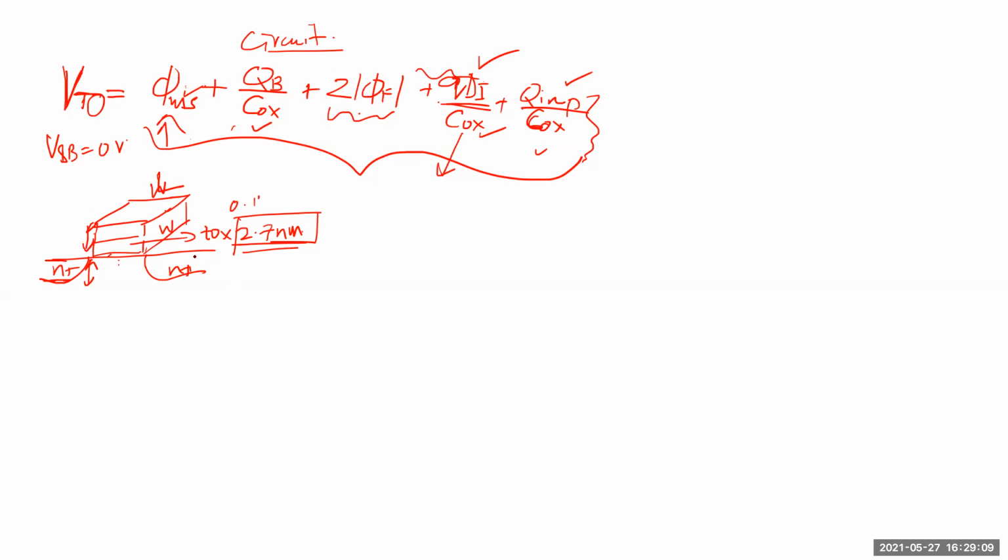If you are a process engineer in TSMC, or in India like SCL, which is the only fab we have, or in Intel, or Global Foundries, then you say, I want to do this device which is really fast, has low VT, low leakage, and all that. And then you say, I don't want to heavily dope this. I want to do salicide here. I want to do this. So then the whole world is your canvas to do that. Obviously limited by the physics, but you don't have any control on the vertical direction.